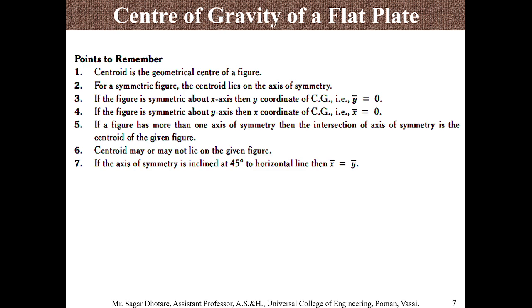So in this case there is one rectangle and four corner radii, you can say 3/4 of a circle. Similarly, identify the symmetric geometries and identify the non-standard geometries first. Then the centroid may or may not lie in the given figure; it might be outside the boundary or inside the boundary.